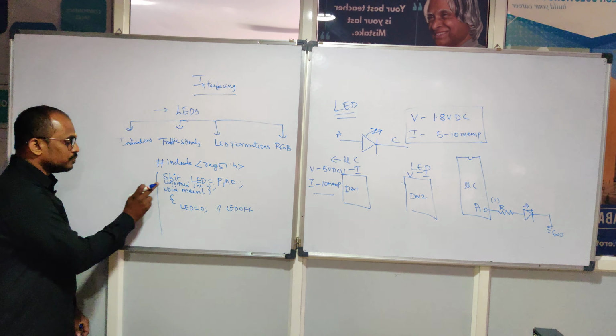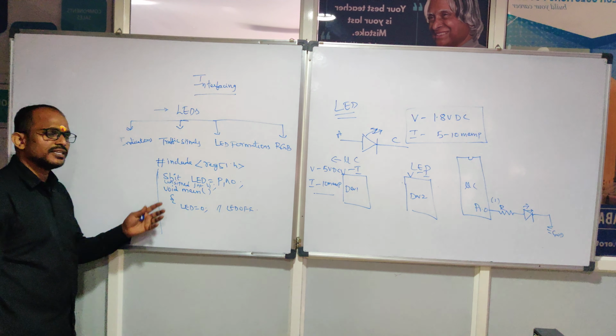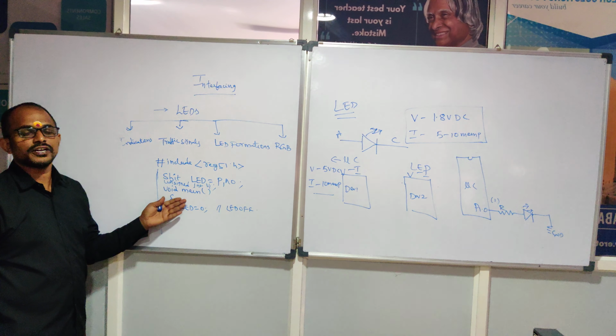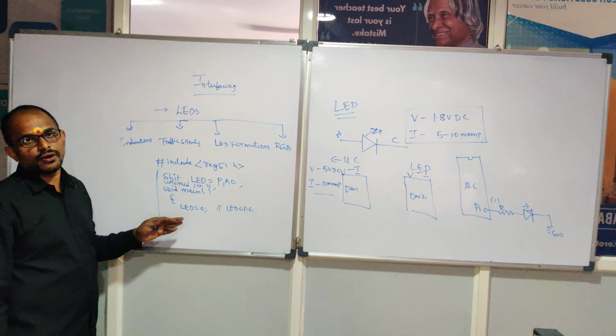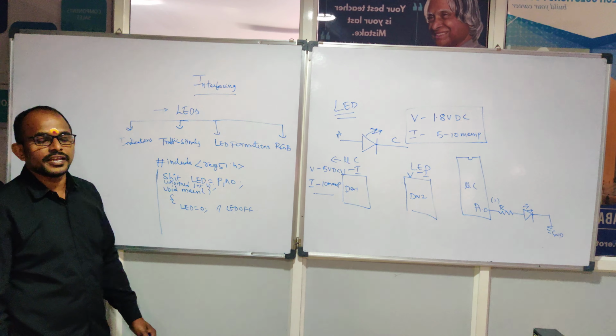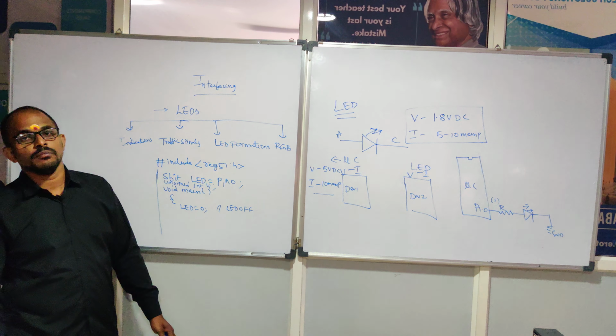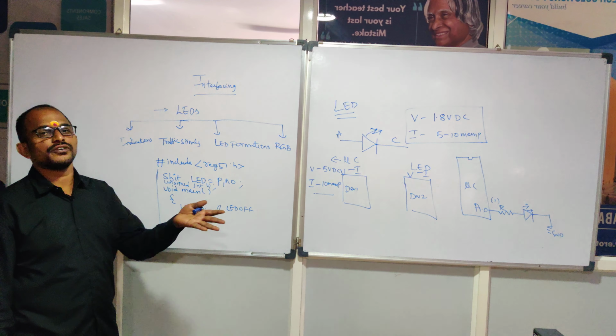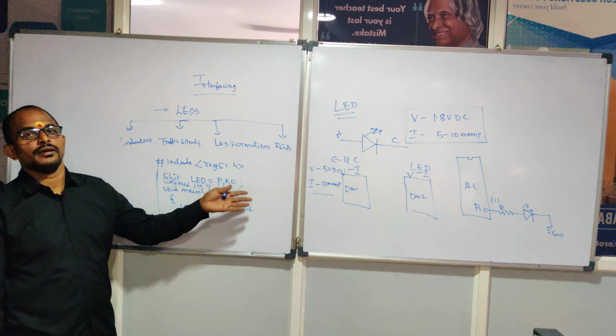So why do you need these delays in between peripheral operations compulsorily? Because they have their own response time. But microcontrollers are very quick. They execute your instructions within microseconds, but your peripherals do not respond in the same time.